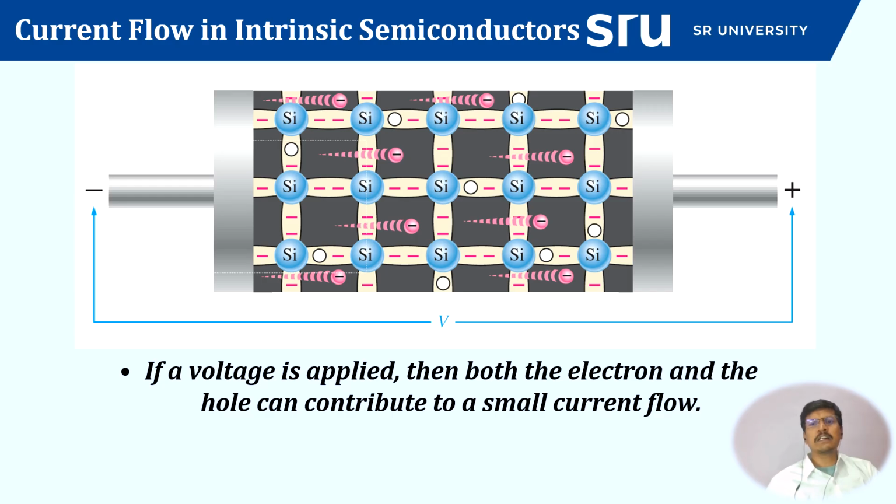This process repeatedly happens throughout the crystal lattice. Holes appear to move through the material, although holes are not physical particles. Their movement can be treated mathematically as the movement of positive charges. This greatly simplifies semiconductor analysis.